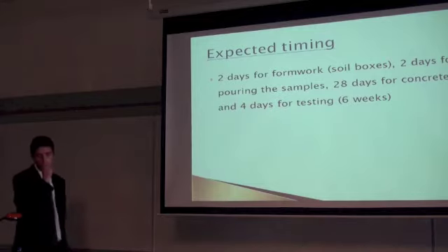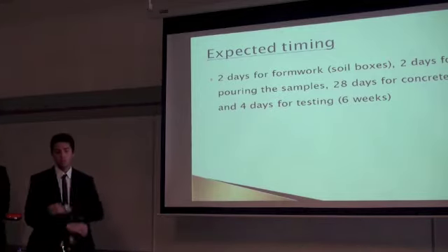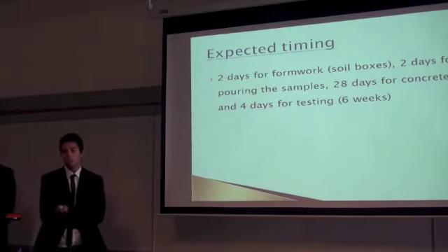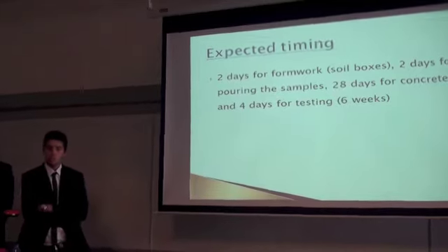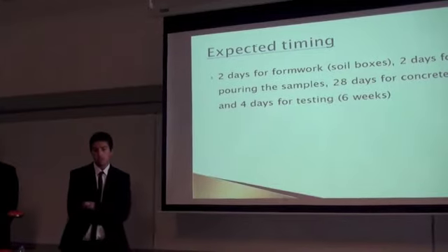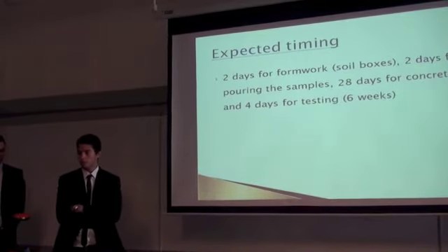Okay, so the expected timing for the whole project is going to be 2 days for formwork, 2 days for pouring the samples of concrete, 28 days for the concrete to gain its full strength, and 4 days for the testing process.